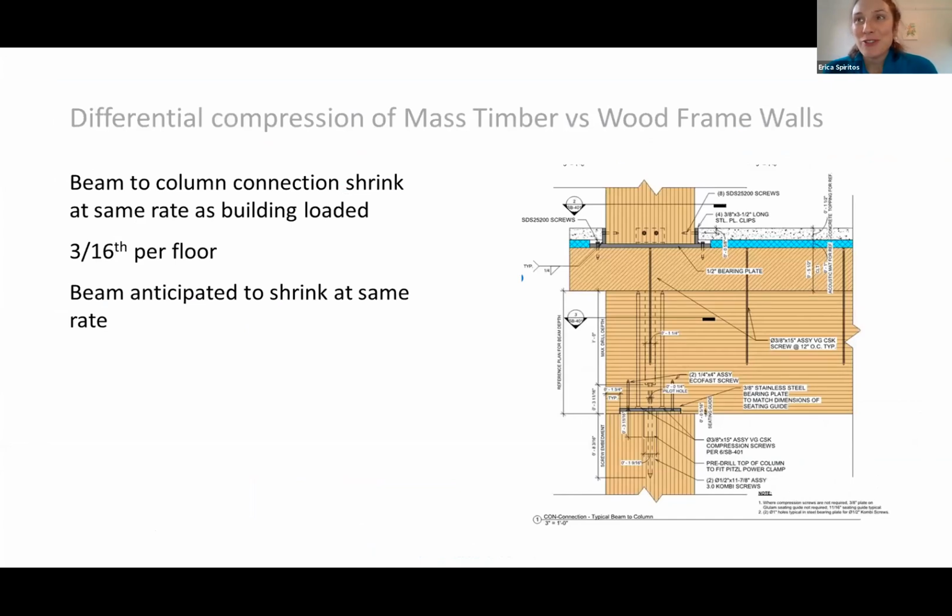So then after we do that 3D geometry coordination, we move into timber detailing. And that's where we get really specific about the timber structure, how all the pieces fit together. We look at material tolerances. We look at movement that we expect or anticipate with differences in behavior between the timber and another structural material that it might touch. We look at the connection detail and tolerances with any steel, fabricated, welded steel assembly that might be integrated into that connection.